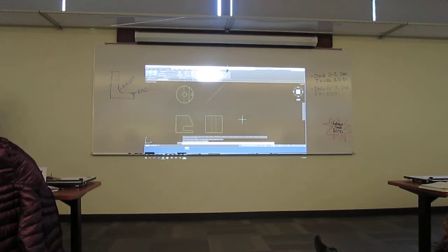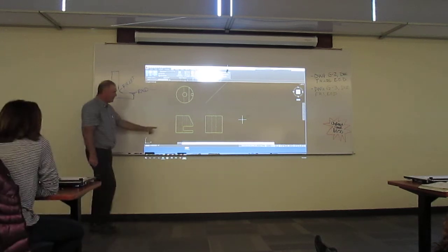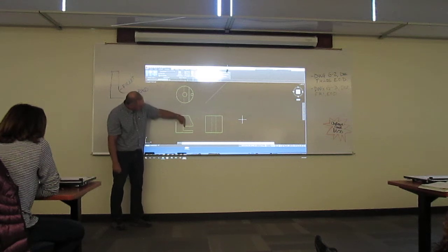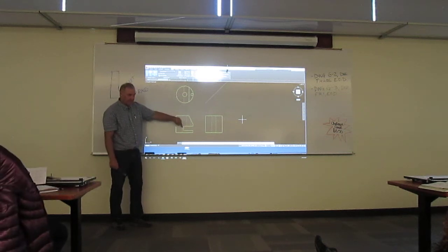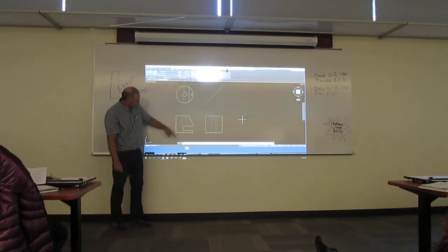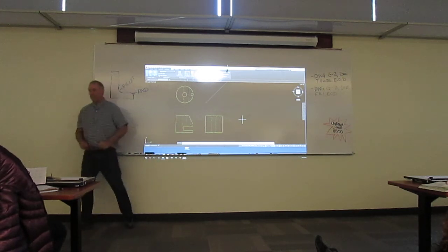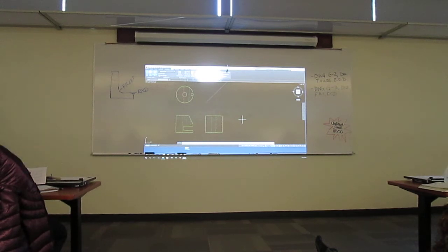Next thing, let's handle this piece right here. Now again, you want to pay attention. Here's that center line. It's back behind it. So we're going to have some things that affect. This thing comes out and it affects this negative cylinder. It also affects this positive cylinder on where it's going. So the first thing I've got to know is my height of it, and I can project according to rule 1 directly into it, so I can bring these over. So there it sits.